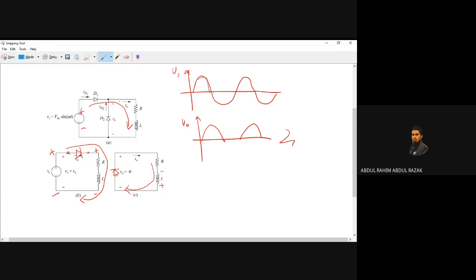Just now when the current flows in, the inductor has positive, negative polarity. But when the source is taken out, the current that remains inside your inductor has to flow out, and it flows into the diode, which conducts when forward biased.